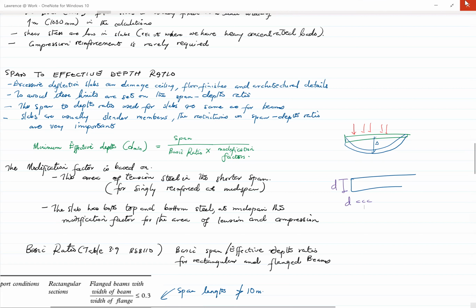Okay, you don't want to finish your bending, find your M, find your AS, and then also do the detailing or find the reinforcement, and then later you come and do the deflection check, and then you realize that your slab is not passing the deflection check. And once it's not passing, you have to go back and change the size of your slab. And once you change the size of the slab, you have to do the design of the bending all over. Okay.